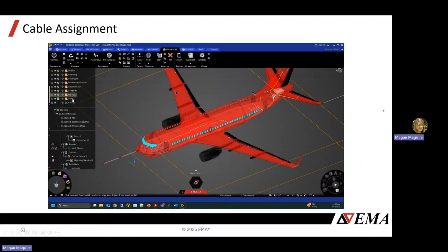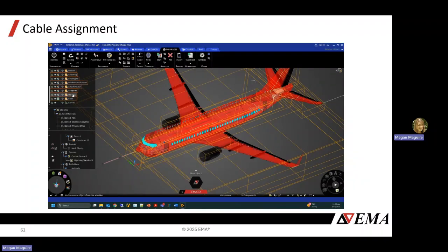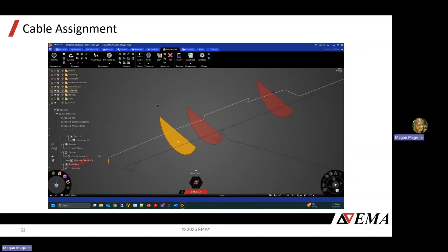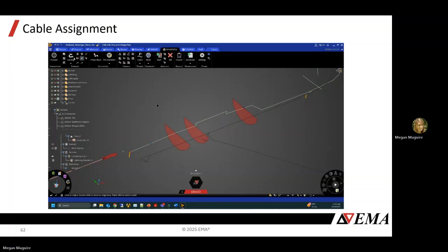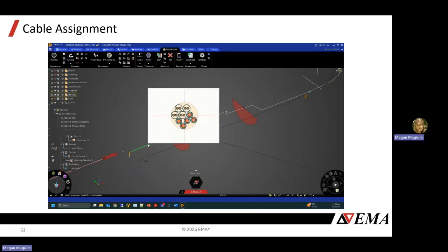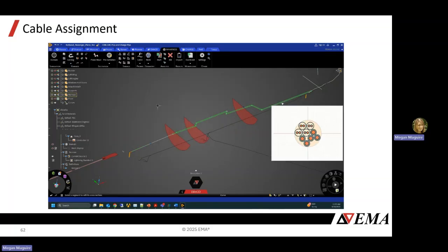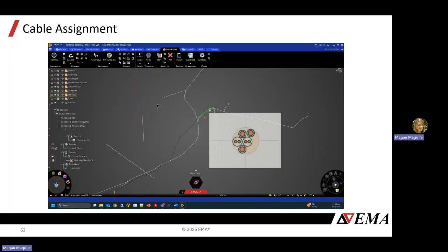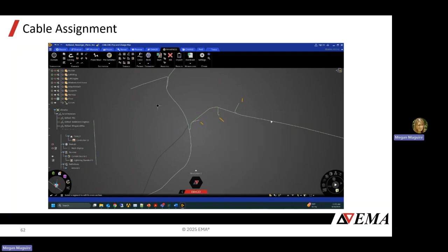So in this video, we'll hide the outer structure initially to have a better view of the cable routing and the internal bulkheads. Then zooming in, go to your M harness tab. You can actually inspect existing harnesses to see what sort of cables exist in those lines. That can be helpful for seeing branching, seeing what you've already modeled, or just creating images of cross sections.